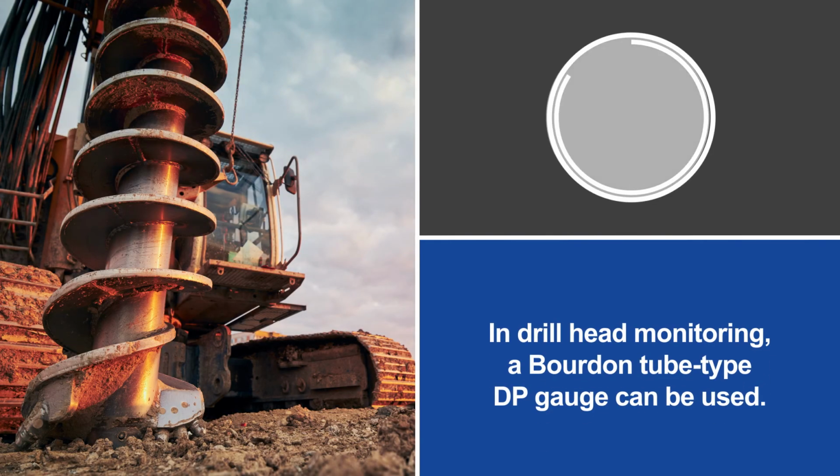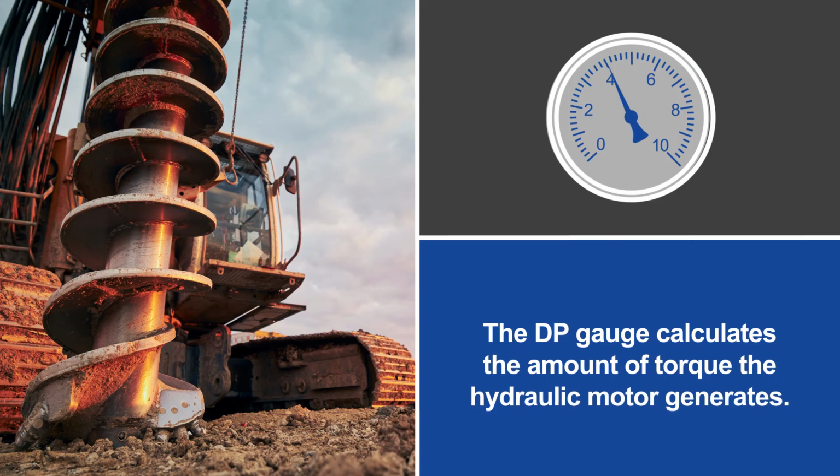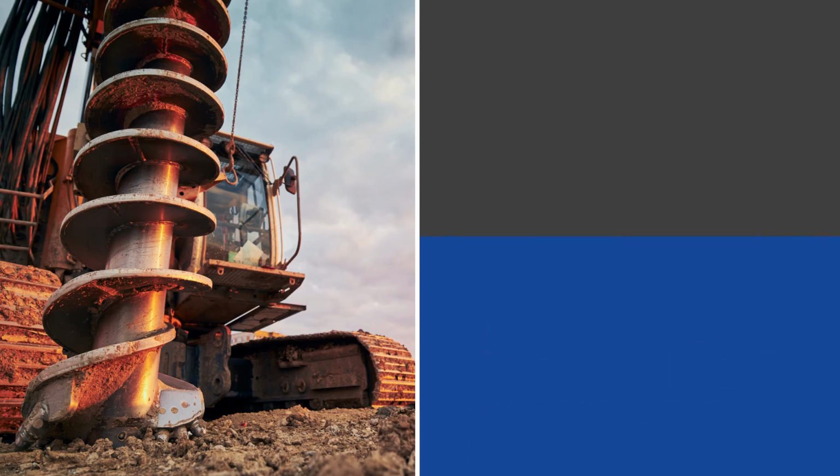In drill head monitoring, a Bourdon tube-type DP gauge can be used for monitoring hydraulic motors by measuring the output torque of positive displacement motors. Through measuring a pressure drop, the DP gauge calculates the amount of torque that the hydraulic motor generates.